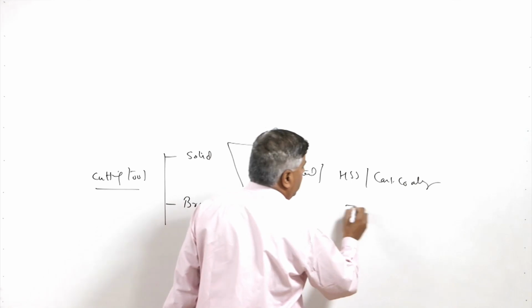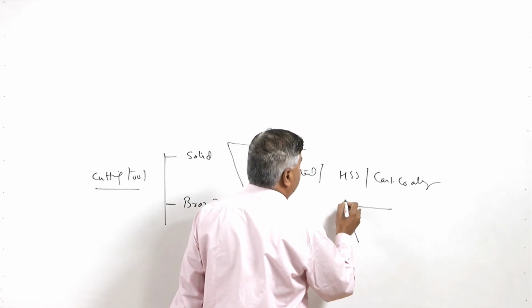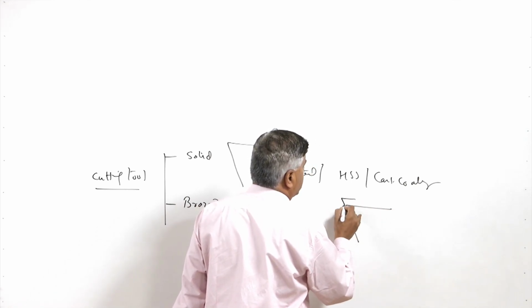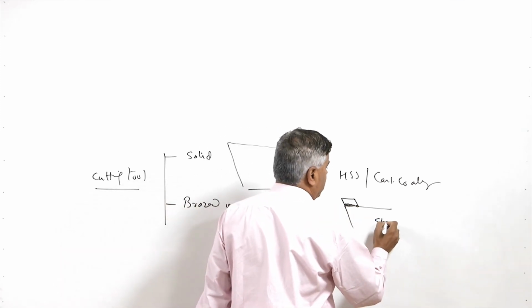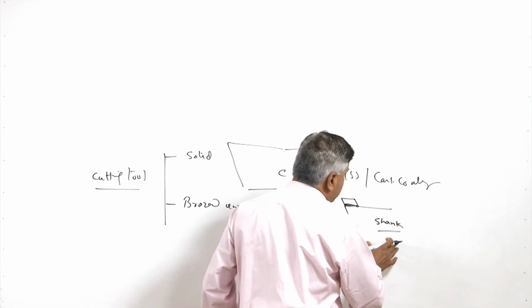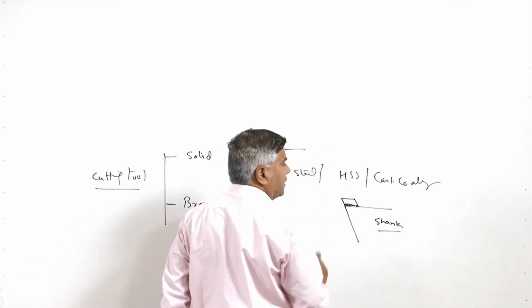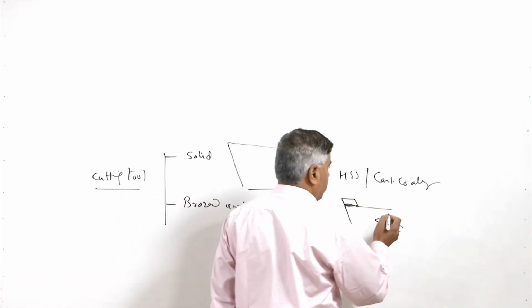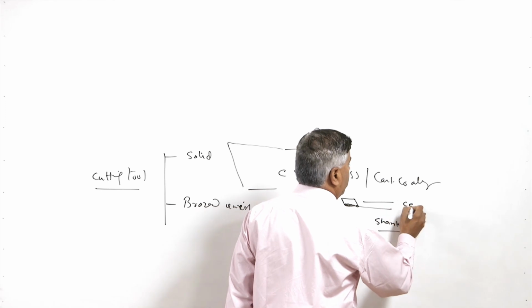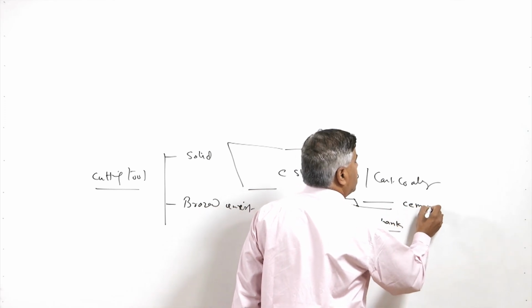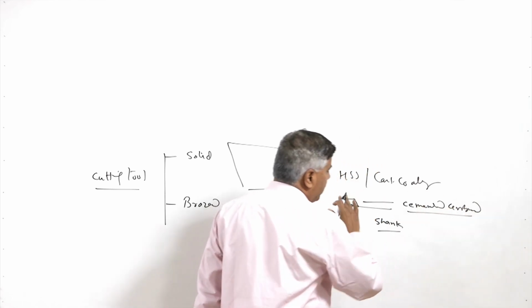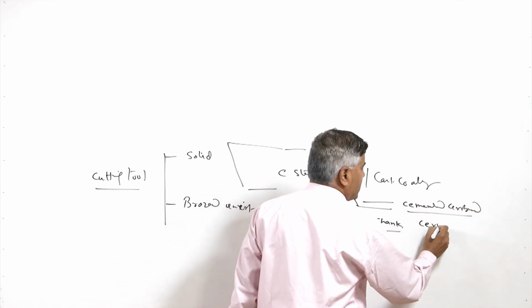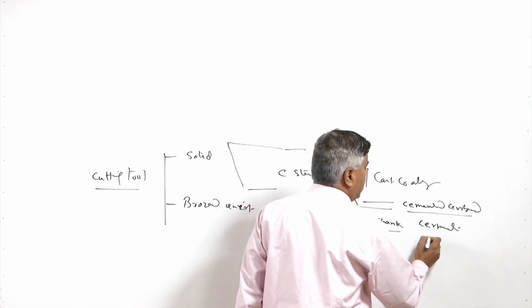on the tool shank we braze the insert. So, the insert is brazed like this on the shank. Here the shank does not interact with the workpiece, but the cutting tool insert interacts with the workpiece, and this is normally used for cemented carbide, cermets and ceramics inserts.